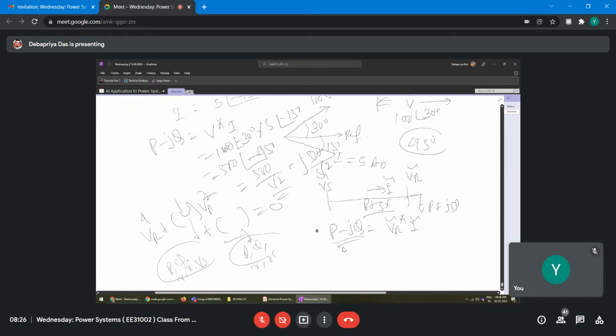At least one boy asked, sir, why are these 3 solutions not feasible, and only one solution is feasible? So I explained to him, whatever data is given, you have to look at what our power system needs, right? Our standard voltage levels for power systems: the highest is 765 kV, 1200 kV is also there in some countries, then 400 kV, DC is there, but generally 220 kV, then 132 kV, then 66 kV, then 33 kV, then on the distribution side 11 kV, right?